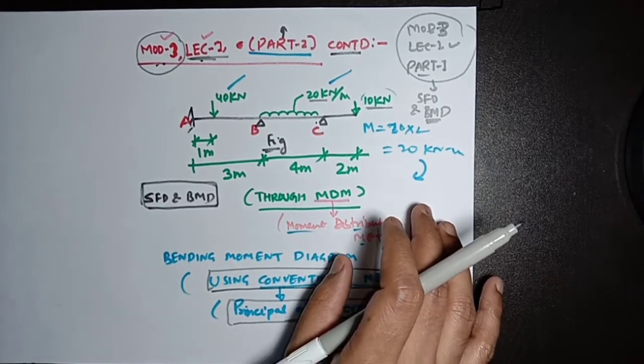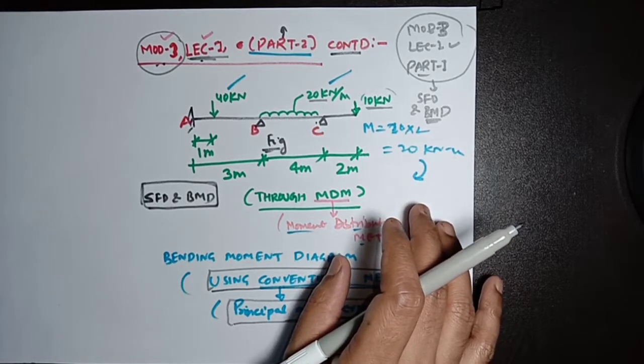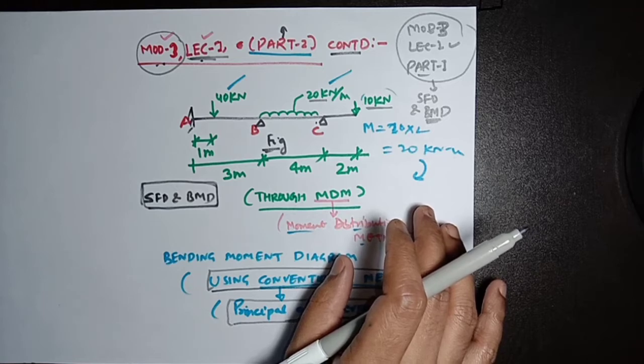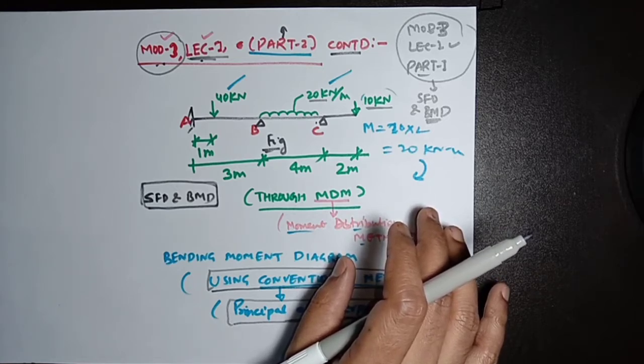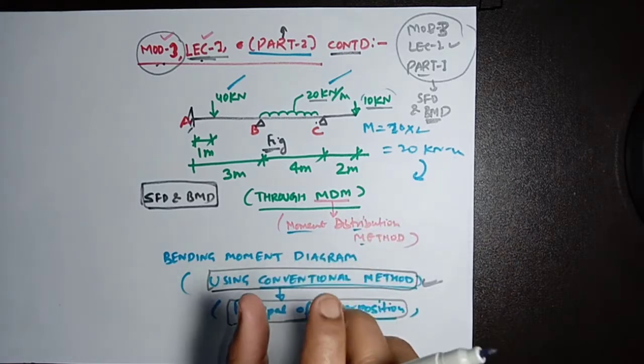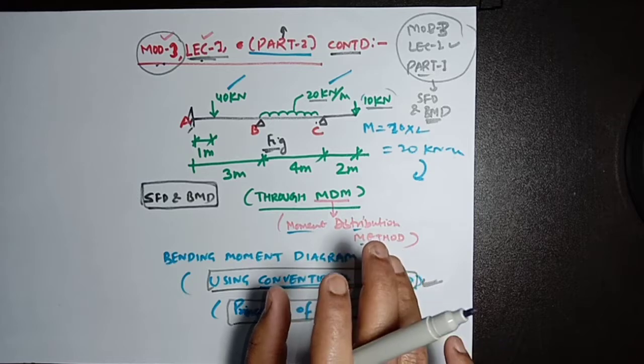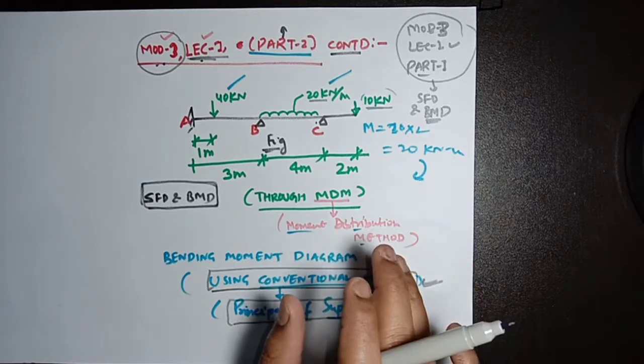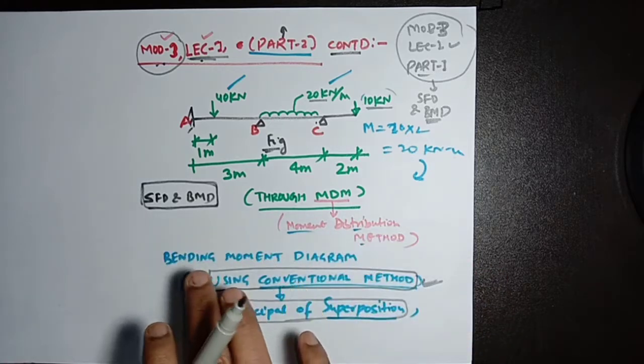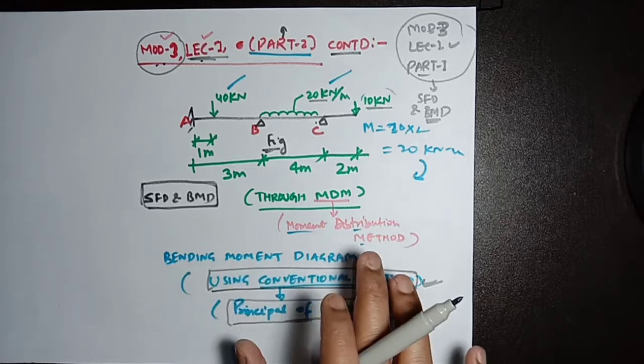If somebody asks you to form a shear force and bending moment diagram, then it is very easy to form the bending moment diagram through the loading diagram, because first, if you are going to develop a shear force diagram, you need to find the reactive forces. Then, after having all the reactive forces applied, you have the applied loads and calculated bending moments through the bending moment charts, you can develop a bending moment diagram.